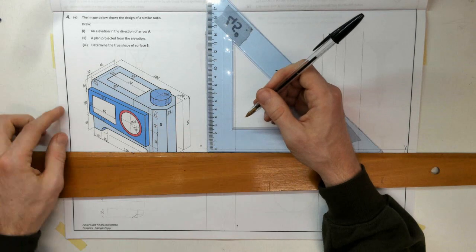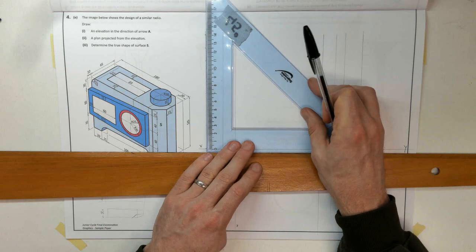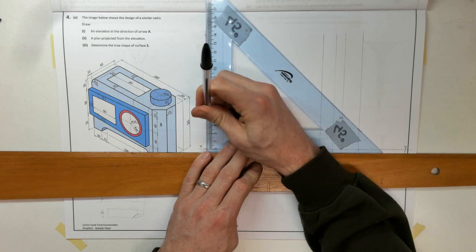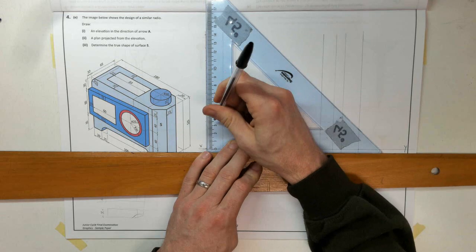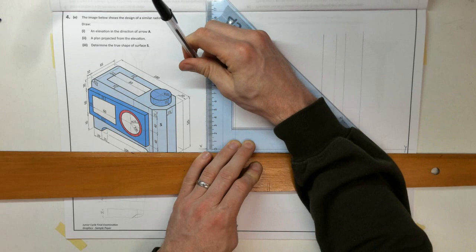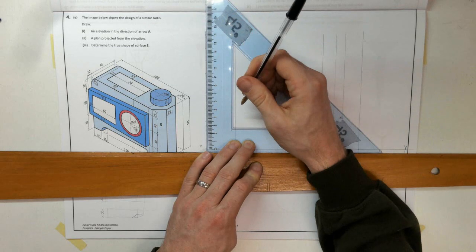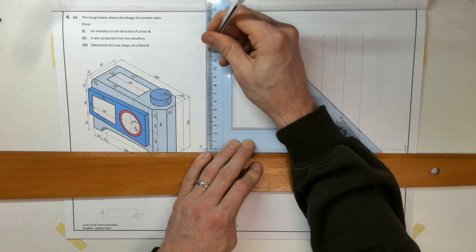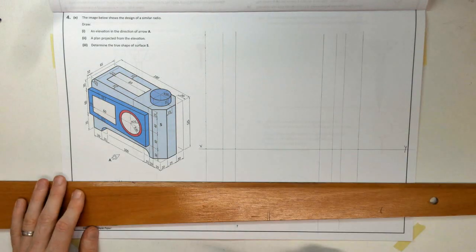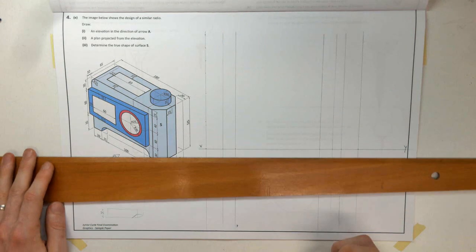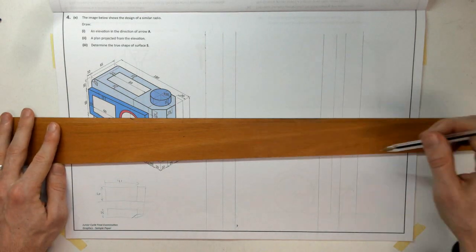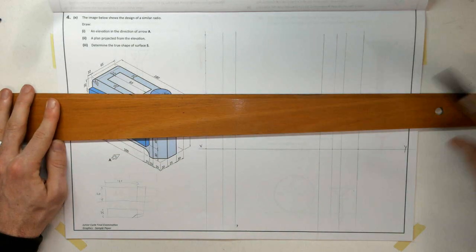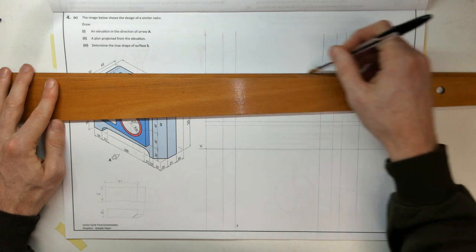And then we also have a measurement of 35 on this side, I'll come up 35. 35 plus 60, which is going to be 95. That's for that sloping bit. And that leaves me with 30, which it does. Okay, there will be other measurements again, but we'll just go with these for now. So if I was drawing an end view, I would extend over to my end view also.